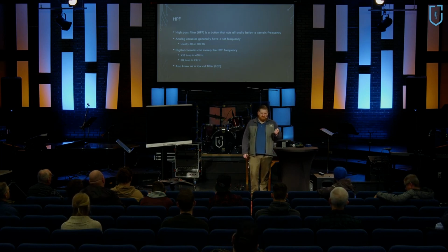So generally with drums, I actually gain them up to about +10 on the meter, because the RMS value, the average, is then closer to 0. And as long as it's not clipping, you're fine. You want to leave some room, so you want it as high as you can get with room so that they don't clip if they get louder.